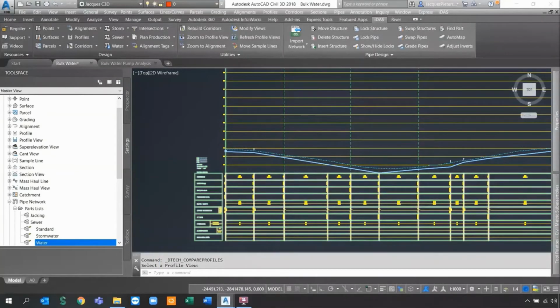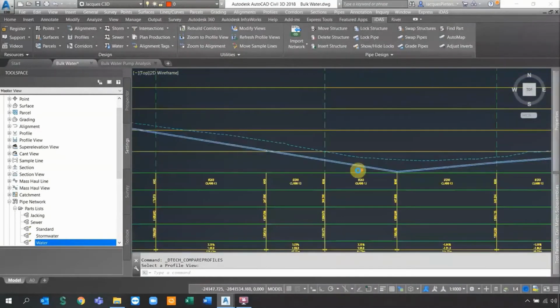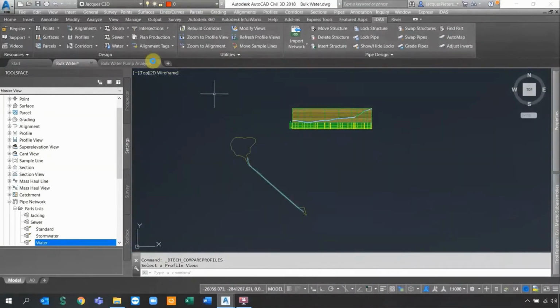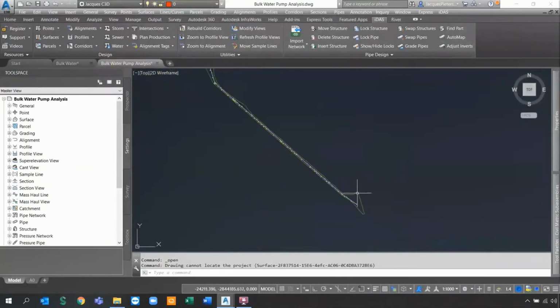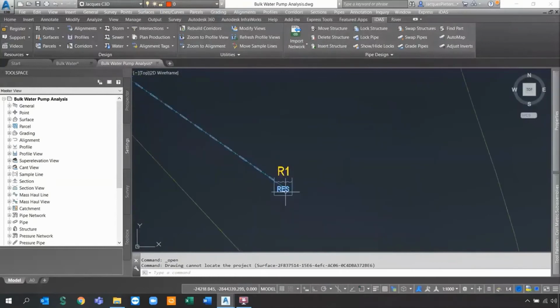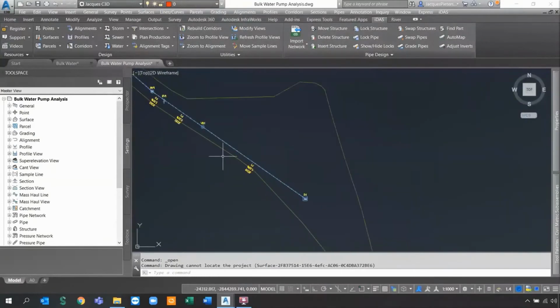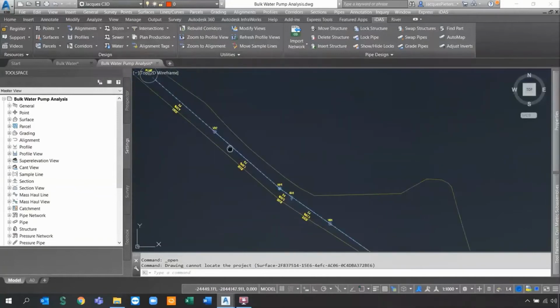So after you've added all of the structures, you can actually go swap elements out. You can still add pumps, air valves, and all of those things. I'm going to jump a step because I'm just cleaning this up. You can add labels to these things, and I just made it much prettier. So I've now added annotations as well as data for the pipes, but I want to move on to the next step for the actual analysis part.